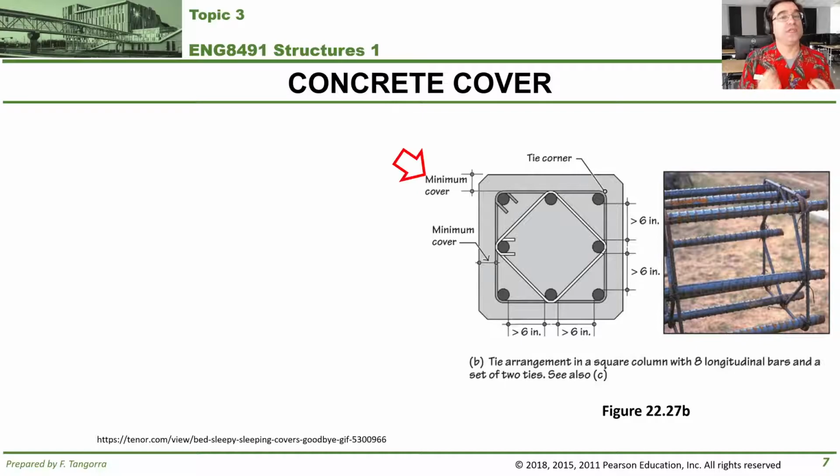And because concrete is designed, for the most part, to be somewhat porous, that is, water can go through it, when water goes through it, it can carry salt with it, but it can also get on top of that reinforcing steel that's close to the surface. And if that happens often enough, then you can get rusting of that reinforcement steel. And when rusting happens, this chemical reaction happens that gets the rebar to expand and crack the concrete.